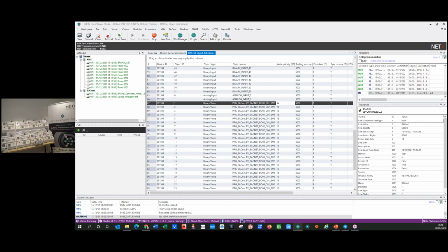And if you have some devices, this is a BACnet specific thing. If you need to test a different position to write an item, because maybe you write and it's not working, you can check it. You can change this, for example, to a different priority number 9 or even 8, that is put a 7. And also you can do this, and this is very interesting to check.